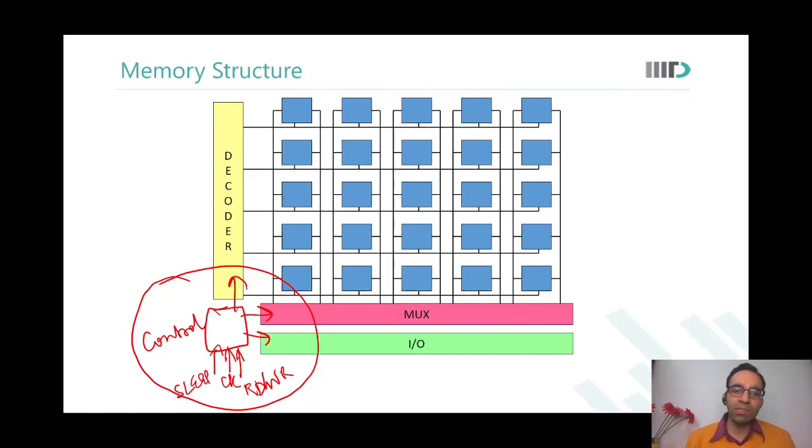Okay. So in CA, you talked about MDR and MAR, where addresses were also, let us say, 8 bits only, and data bus was also only 8 bits. But for an SRAM, if there are 100 or 1000 locations, how many address bits do you need to decode? 12, 10 or 9 or 10. You will need 10 address bits. So what that means is that your system processor will send the overall memory address in 2 cycles. That does not mean that your memory will have only 8 address bits. The processor has to send all the required bits. How it sends it, it is the protocol that the processor will set.